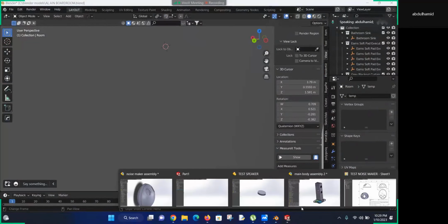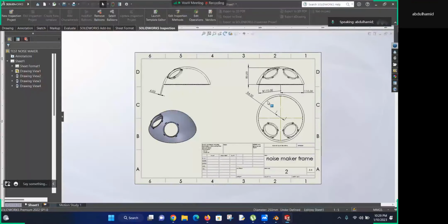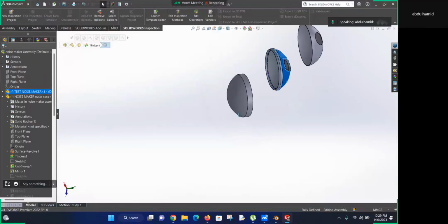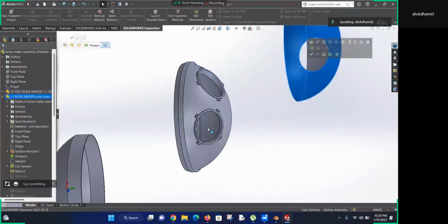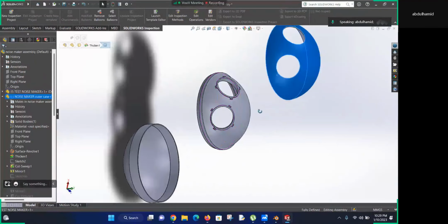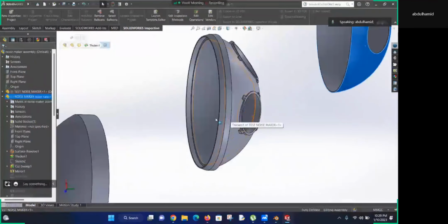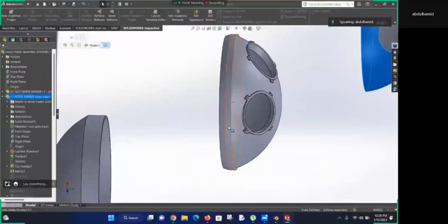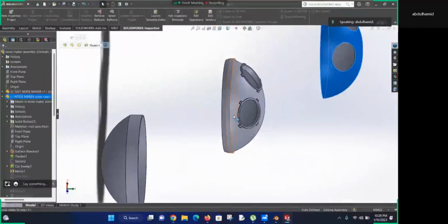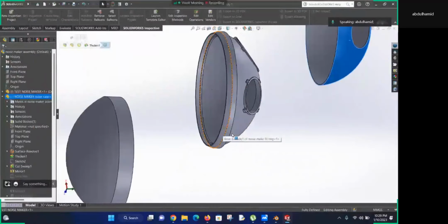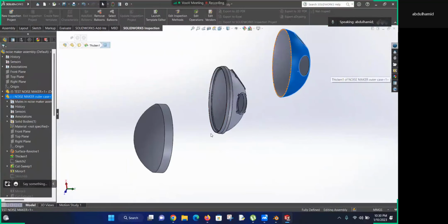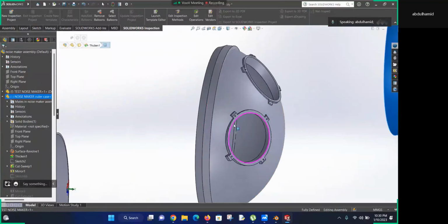If you go to SolidWorks, for example, you cannot just model. It allows you to be creative also, but you need to be very conscious of what you're doing. Take, for example, these two components. I had to make sure the diameters of these two components leave just a gap, a tolerance of, let's say, 1.2 or so millimeters between them. If the dimensions are not coherent at all, let's say this is way smaller than what the dimension of this is, you will see the mates will not be accurate.